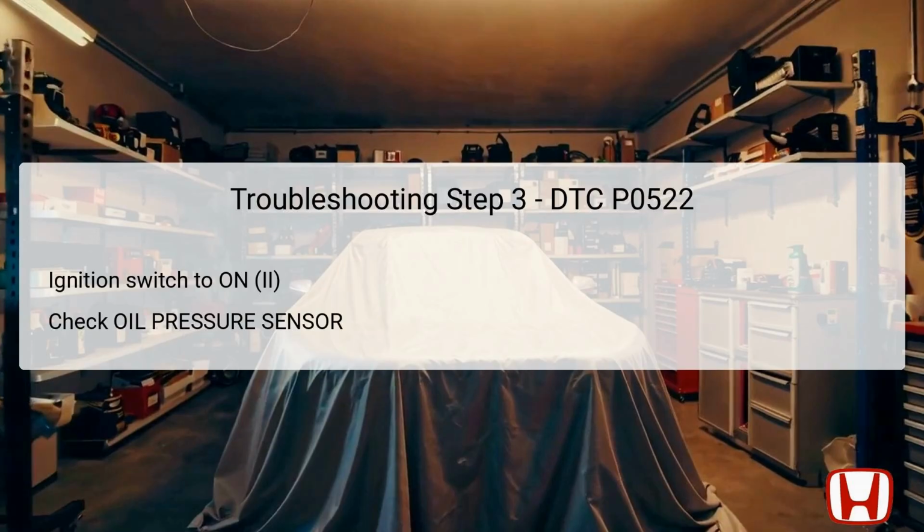For the third step, once again, turn the ignition switch to the on position, marked as 2. This action will energize the electronic systems within the vehicle, allowing you to take another reading from the rocker arm oil pressure sensor. You need to check the HDS data list for the sensor's voltage.